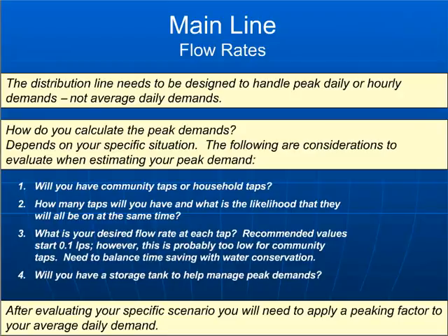And so you can imagine in the morning, everybody gets up and wants to go and get water to get things started for the day. People are going to go to the taps at the same time, open up a lot of tap stands at the same time. And so you need to make sure that you've got sufficient piping present to handle that peak demand.